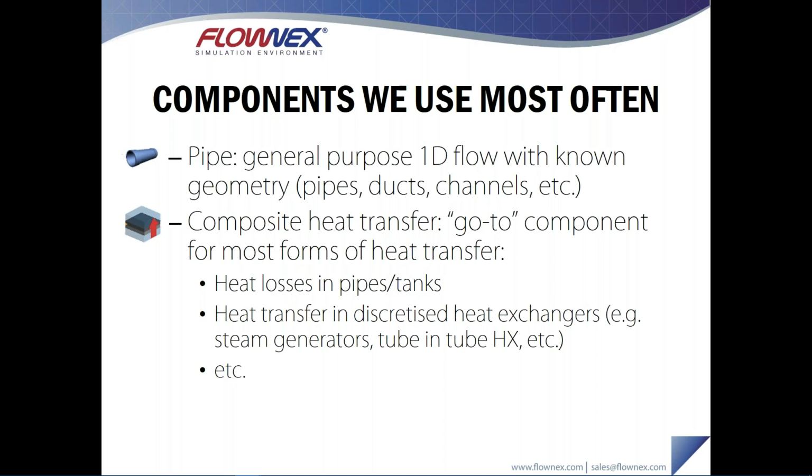I find that it's most useful when modeling convection, conduction, and convection again. So for example, heat transfer from the inside of a pipe through the pipe wall. You can account for different conduction layers. So you could account for the effects of fouling by using this component very easily. And then account for the convection on the outside of the pipe, be that into another fluid or into ambient conditions. This component is very easy.